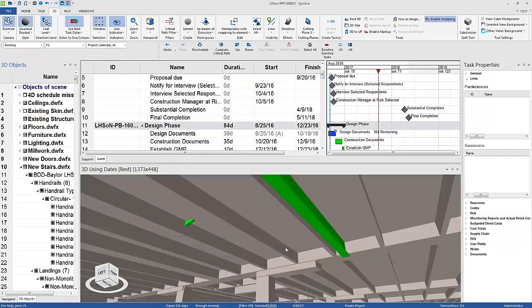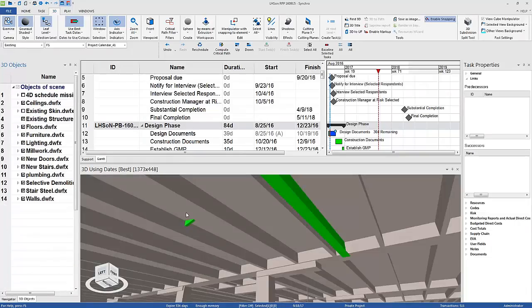the skin. So yeah, obviously when we export out of Synchro, it's very important when you're exporting out of Revit, or if you're using a Revit plugin, to do it by views, because you want to be able to isolate and turn things off. You can set filtered views inside of Synchro as well. It's just easier because it's a one-stop way of pushing views out of Revit. It makes it easier, right? I don't have to manually do those inside of Synchro.